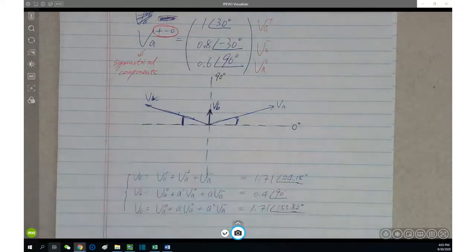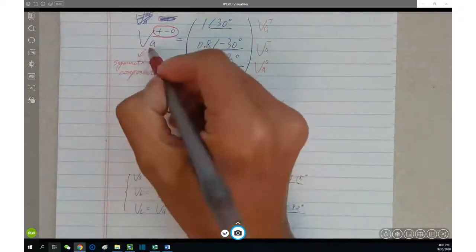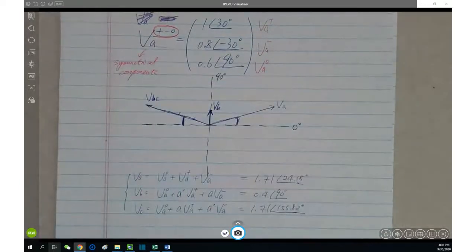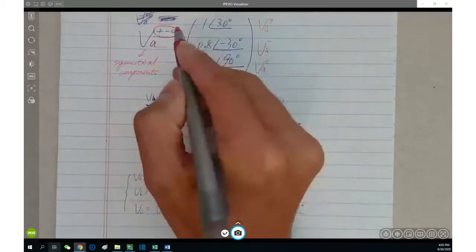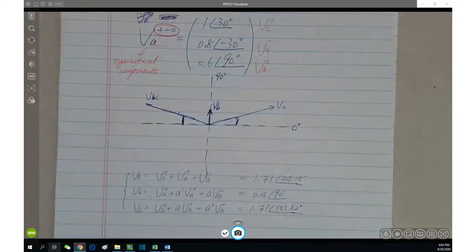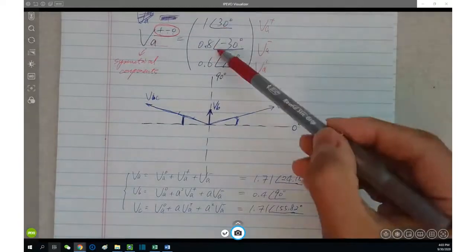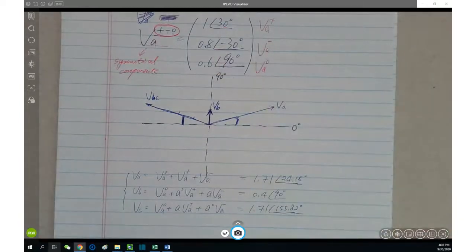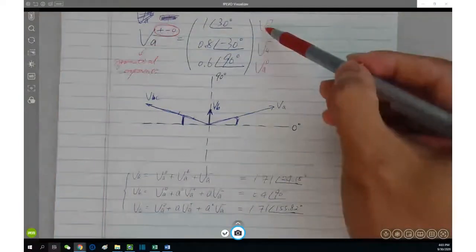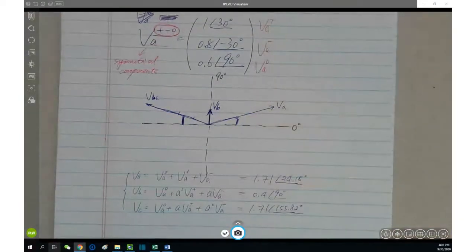So symmetrical components means, first of all, we are talking about voltage, phase voltage, and the phase A voltage, positive, negative, zero sequence components. Inside of these symmetrical components, everything is phase A component, just for different sequence. So there are two concepts. One is phase, different phases. We have three phases, A through C. And then we have parallel three sequence components.